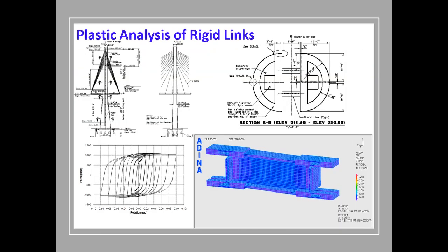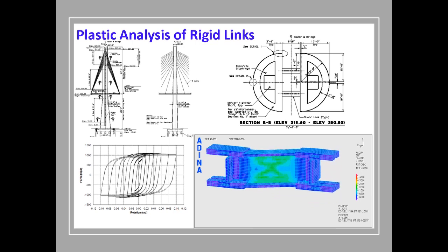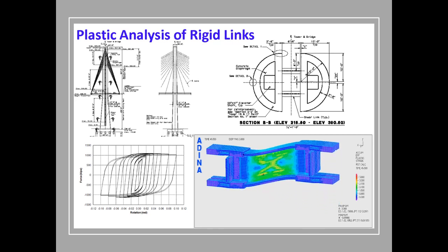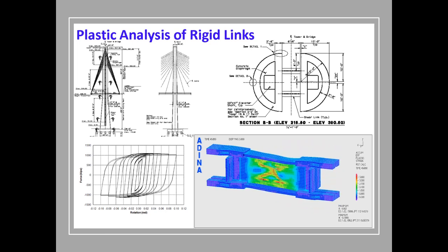The design of a cable-stayed bridge's pylon in a seismic region included installation of sacrificial link elements within the pylon to yield undamaged during a potential earthquake and safeguard the pylons from damage. Thorough testing was done during the design and optimization of these link parts under cyclic drifts, which could advance by up to 0.10 radians. Finite element modeling was used to conduct the experiments, which greatly reduced the amount of time needed to set up a lab experiment for this purpose. The connection elements' cyclic behavior and the development of plasticity are demonstrated.